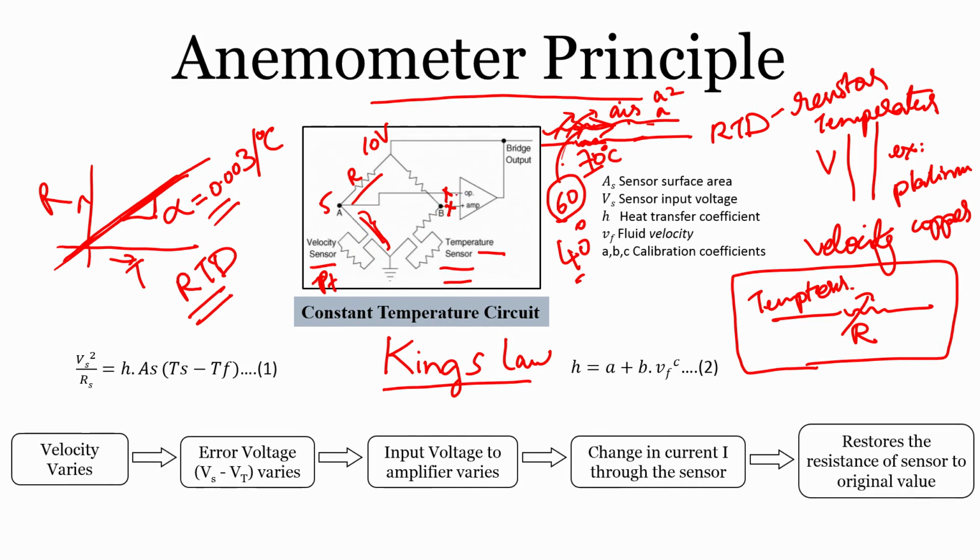However, this is always compared to a reference 5 volt, and a decrease will forcefully have a feedback such that the additional voltage is pumped in, and the increase in current because of the pumping of voltage, the higher I or the current flow through this, is going to bring it back to working at 70 degrees Celsius.